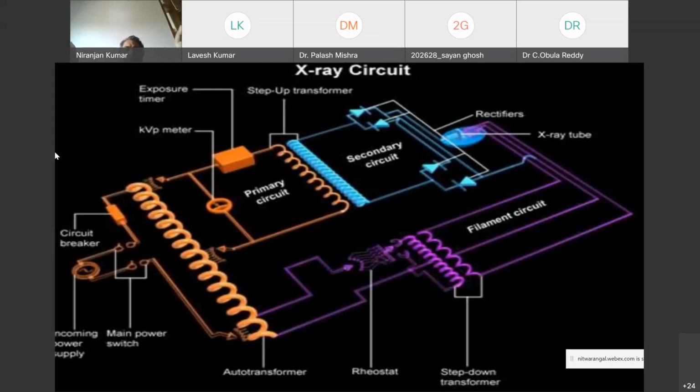Okay, and then there is some switch control auto transformer, which, if you need high voltage, gives the higher voltage through the auto transformer. If it is low voltage, some kind of things, right? And then similar things for the filament. But the filament, since it is at the cathode, there is also some kind of isolation transformer. So whatever the kV comes between primary and secondary, there is an isolation of that much. And then it is also based on how much you want to give to the filament. There is a kind of rheostat, you do that. So this is how it started.